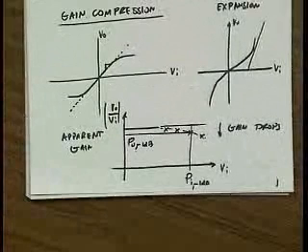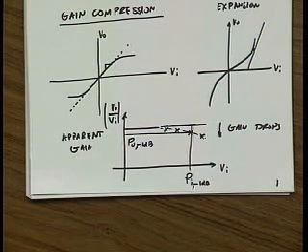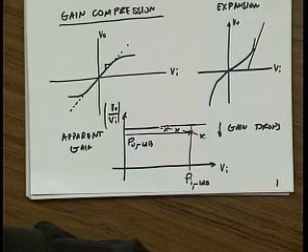It really depends on the standard of communication that you're using. So if you're using let's say a modulation scheme that has constant envelope, then you could go all the way up close to compression if it's just a single tone. This question, there isn't a simple answer. It really depends, right?